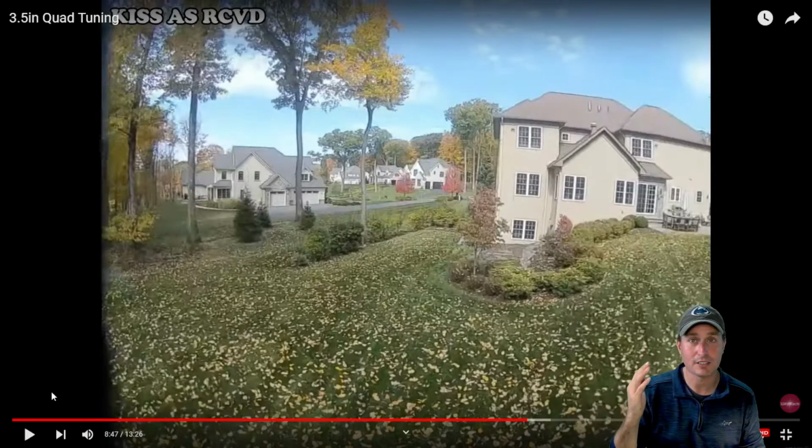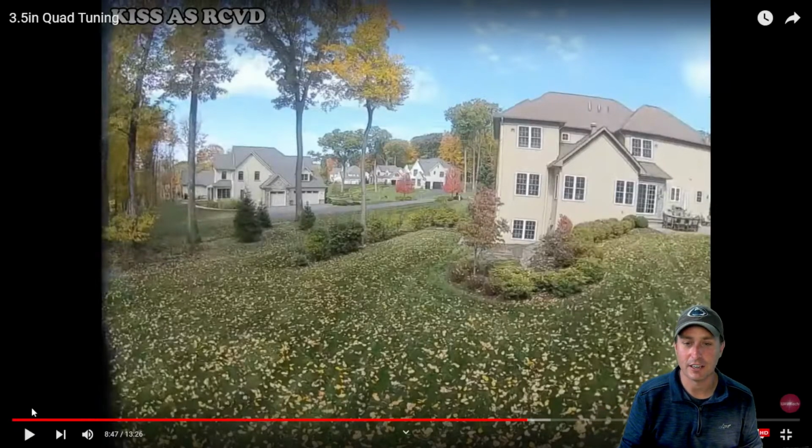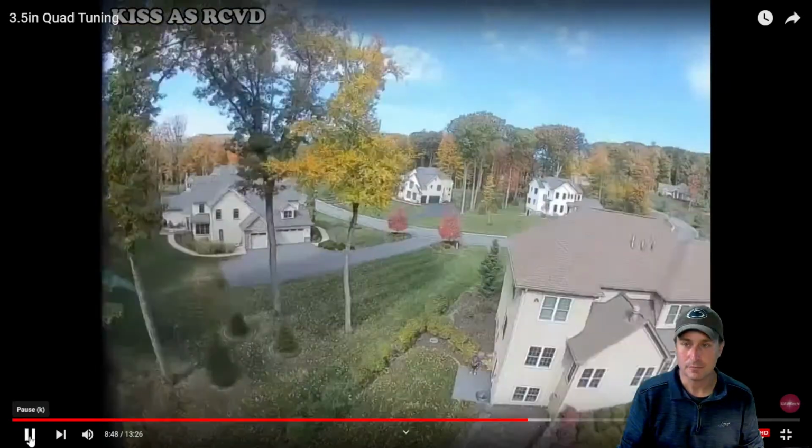And then move P up as high as I could. Any higher on P, you also get flutters, which kind of kick in with prop wash. It will start to flutter and be extended, instead of a quick brrr, it keeps fluttering. So P couldn't go any higher. And same thing with I. Keep boosting up I, and it would bounce back.